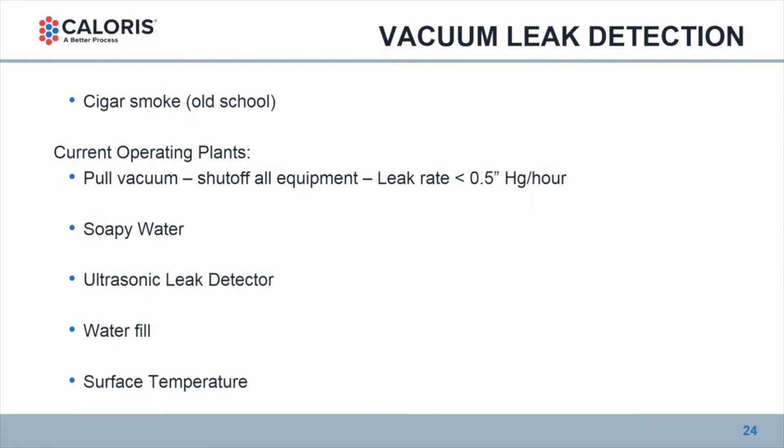However, it is an extremely effective tool when it can be used to fill the shell and/or the product sides of your heat exchangers and your equipment, and that water will show you where a leak is. If you're leaking water out, you're certainly sucking air in when you pull vacuum.